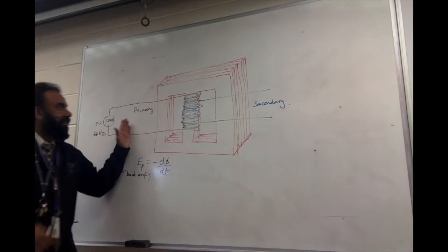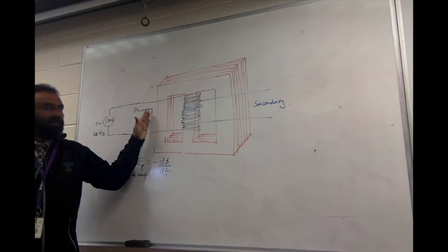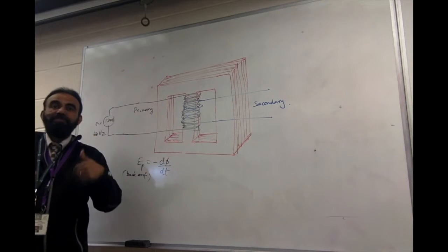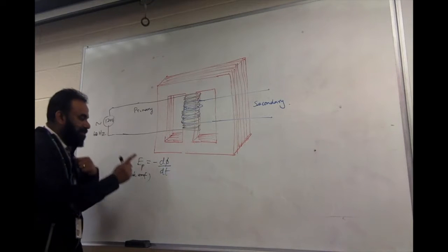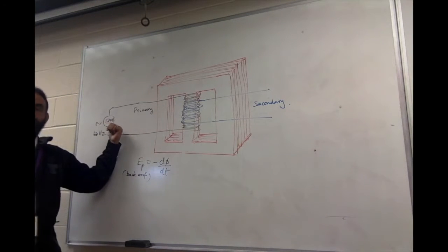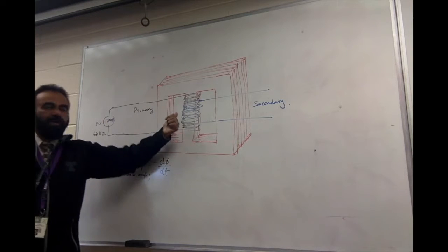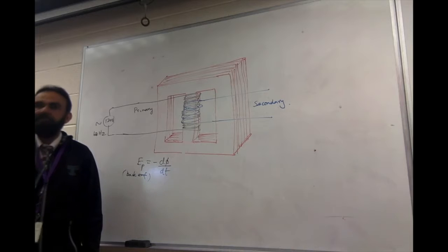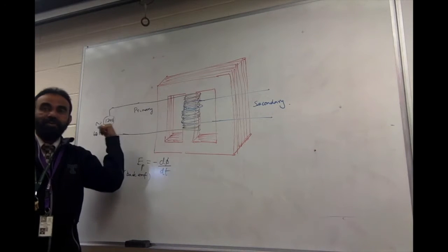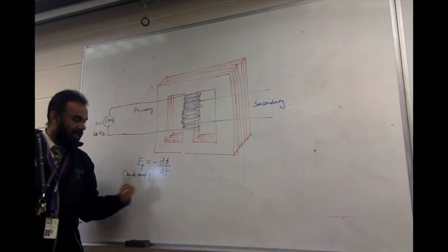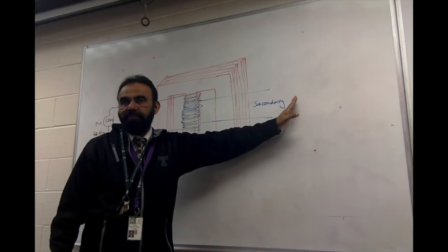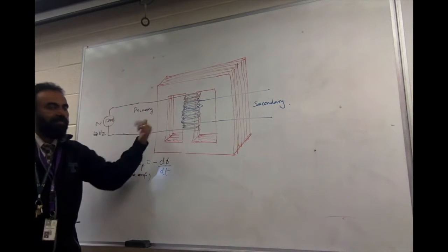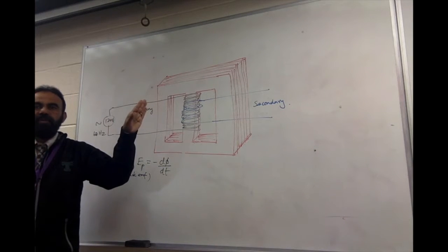Self-induction is when something is happening in the primary, the same primary is subjected to changes of flux, and therefore the same primary will produce this back EMF, which is going to be nearly 120. So if you supply 120, you can get 119.99 return. You can almost get all of it back as back EMF, especially when you don't connect this to anything else. If it's just left open, you're sending something and you get back, no gain, no loss sort of thing.